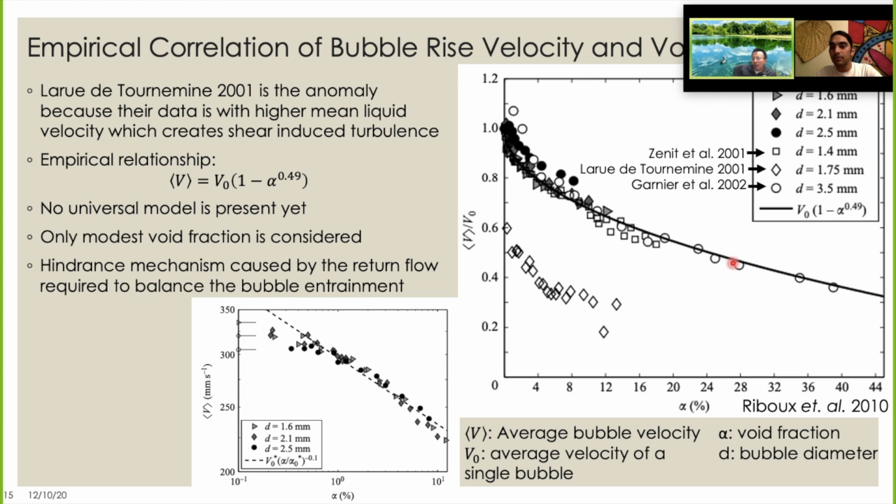Laser Doppler velocimetry assumes you have a bubble or droplet or particle here, and if you shine a laser towards this, it will scatter light. If you capture the scattered light to analyze the wavelength, the frequency of the scattered light and also the interference pattern, you get information about size and also velocity.